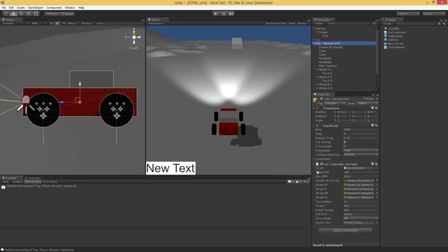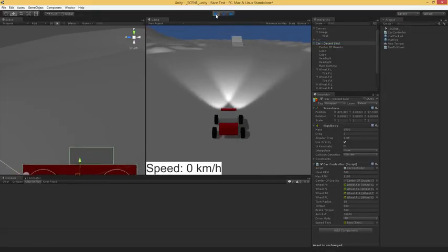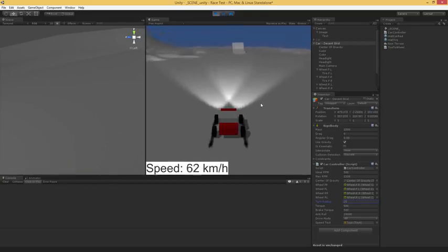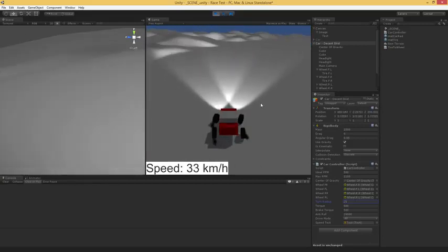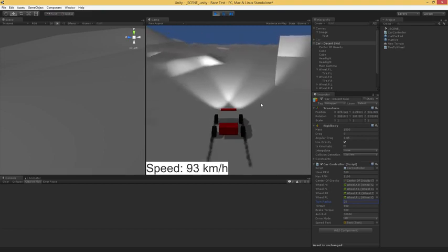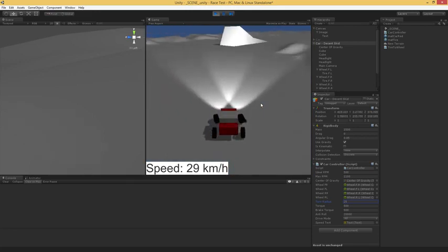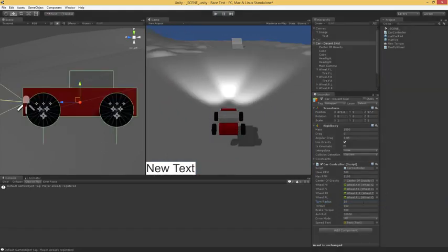Other variables in here. So the ideal and max RPM, the center of gravity. I need a reference to all my wheel colliders, so I just made those public and then dragged them in. The turn radius controls, if I hit full right on my keyboard or my controller, how many degrees turn is that? And right now I have it set to 10 degrees. You can get sharper turns. If we set it to something like 25, I could get sharper turns. But whether that's a good idea or not depends on your speed and skid and stuff like that. Those are pretty sharp turns. You're more likely to flip over, of course, or lose control of the car. Oof. But maybe that's what you want. I don't know. I'm going to go ahead and leave it at 10.